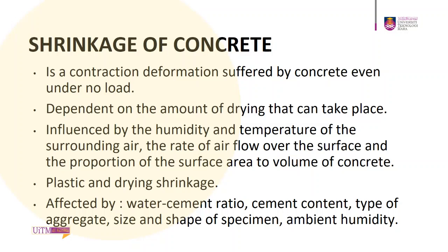So the shrinkage can be categorized as plastic and drying shrinkage. It is affected by the water to cement ratio, the cement content, type of aggregate, size and shape of specimen, and the ambient humidity.